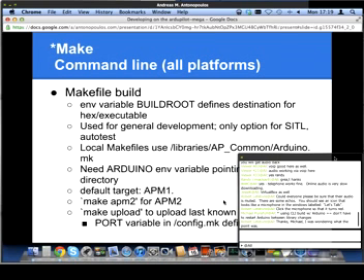Within the makefiles, if you look carefully, you'll notice that it uses a rather complicated makefile, which is in libraries/AP_Common/Arduino.mk. That makefile actually uses some rather complex auto-discovery and search-based discovery process to find where your Arduino IDE is. That helps a lot with cross-platform compatibility. If that doesn't work, however, you can point it directly to where your IDE is by setting the ARDUINO environment variable.